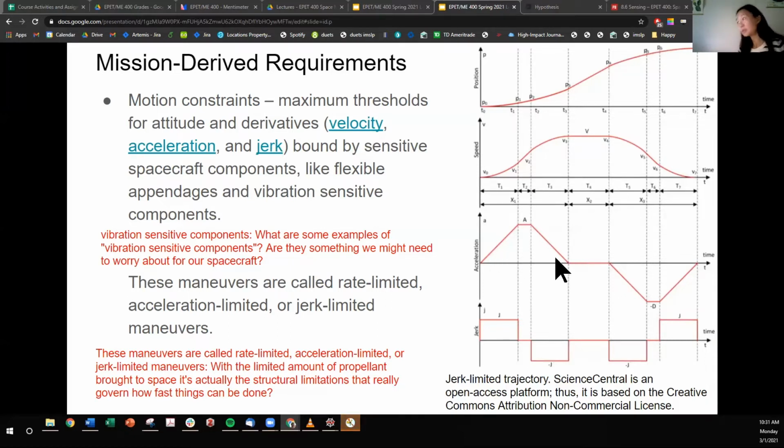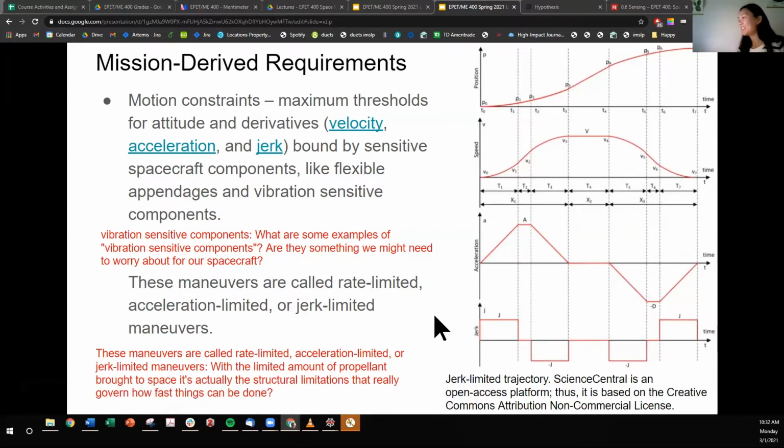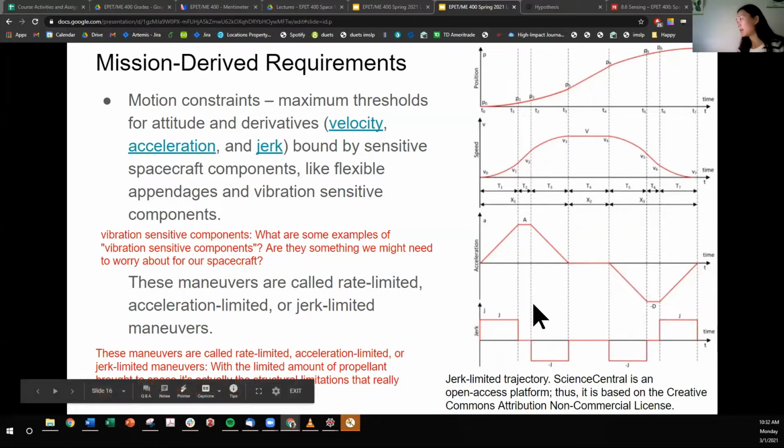Your acceleration profile is going to look like so, where your acceleration is limited by capital A, and it occurs at V1 to V2. And if we get down to our highest derivative, you see these binary steps of the amount of jerk in each time period.